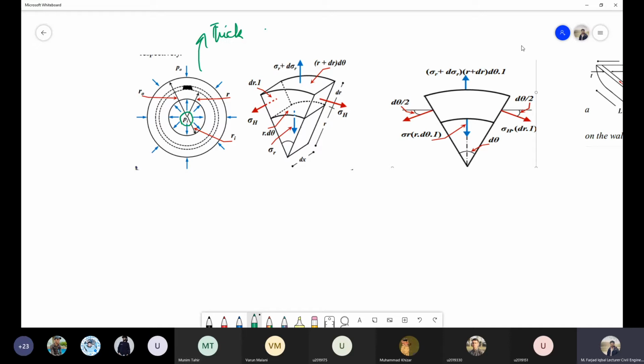And then the second thing is that there may be some external forces also acting on the cylinder. You can imagine that this is a confined cylinder, and due to the external soil maybe present around it, it is also exerting some pressure, and that pressure is denoted by the term P naught. This derivation has been done for each kind of scenario, and in most of the examples you encounter, P naught will be equal to zero. So in the final expression for the stresses, you may have an equation involving P naught, Pi, and the radius.